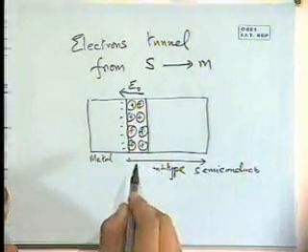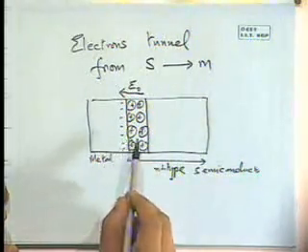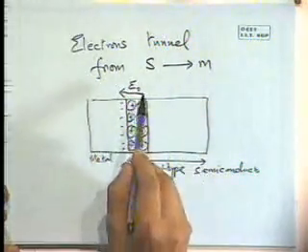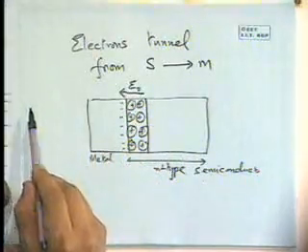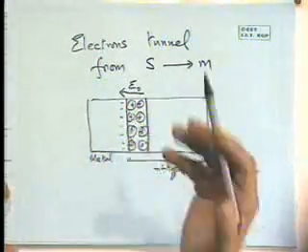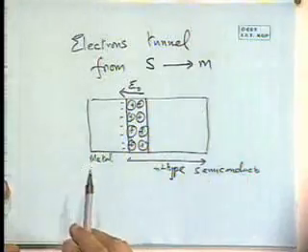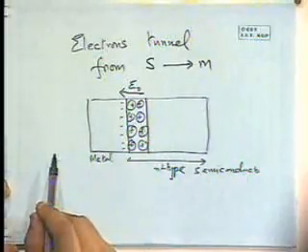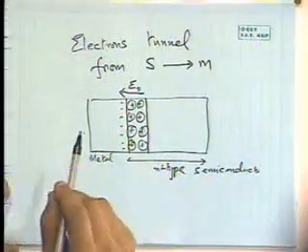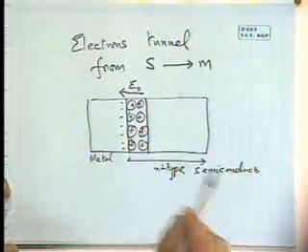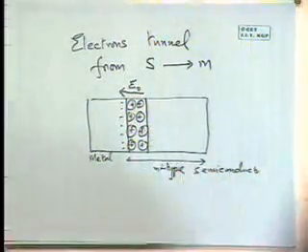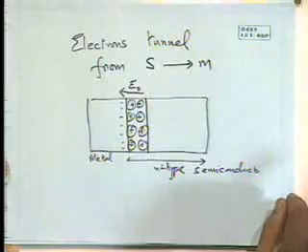and when equilibrium is established, it balances the flow of electrons that were wanting to come into the metal because of the difference in the Fermi levels. And at the end of it all, as we saw earlier, the Fermi level gets equalized. Throughout the solid, the Fermi level must be the same, otherwise there will be energy left for external work to be done.